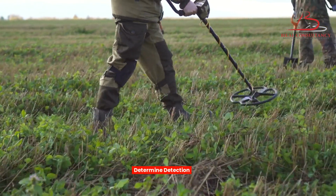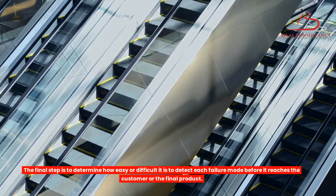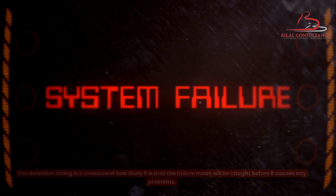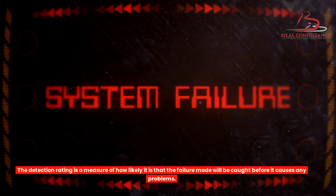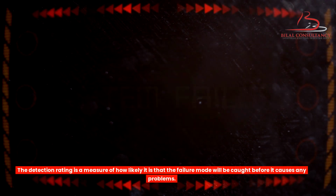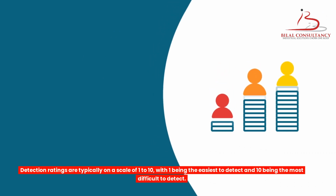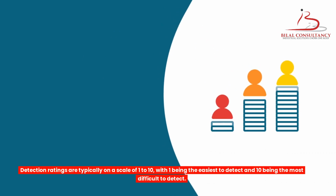Determine detection. The final step is to determine how easy or difficult it is to detect each failure mode before it reaches the customer or the final product. The detection rating is a measure of how likely it is that the failure mode will be caught before it causes any problems. Detection ratings are typically on a scale of 1 to 10, with 1 being the easiest to detect and 10 being the most difficult to detect.